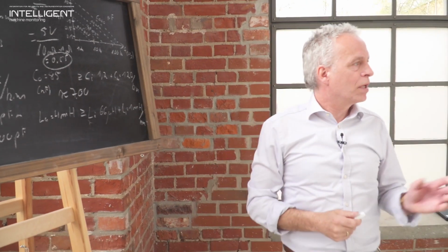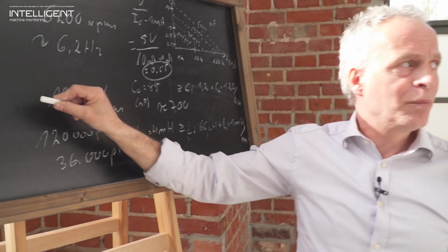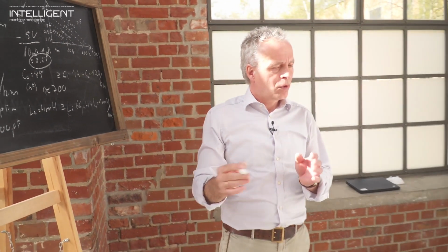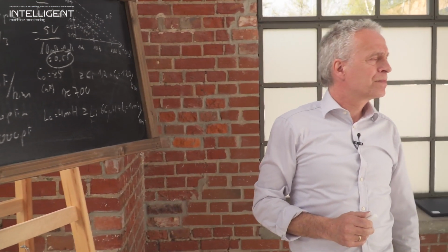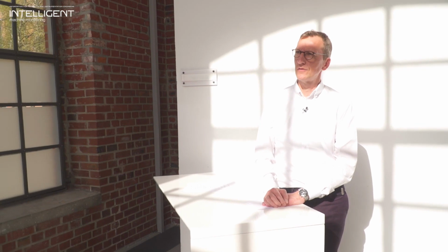Now, what can I do when I need to achieve a longer cable length? If you want to achieve a longer cable length, then you would have to look for a cable with a lower capacitance. Of course, cable with a lower capacitance is more costly, expensive, and then you have to do your calculation, your math, to see which is more economic for you: going to a longer cable, or maybe having this acquisition unit installed in the field, closer to the machine. That's correct. Then you do not have any cable length issues.